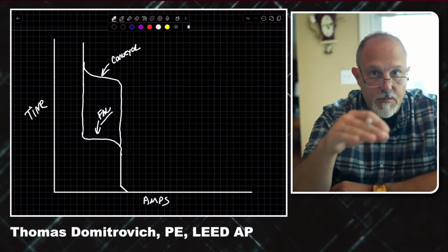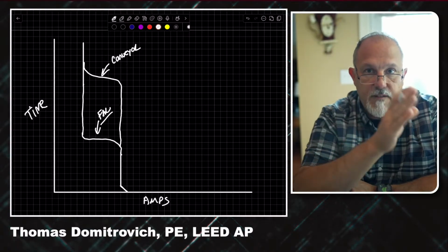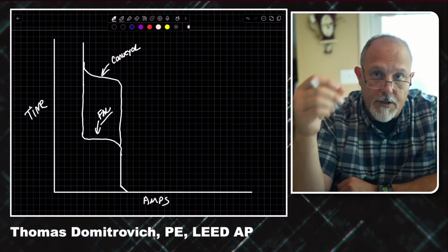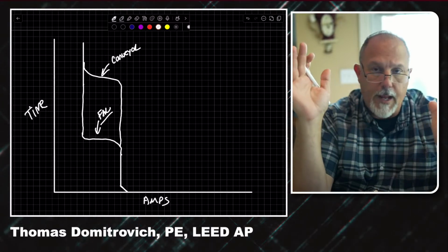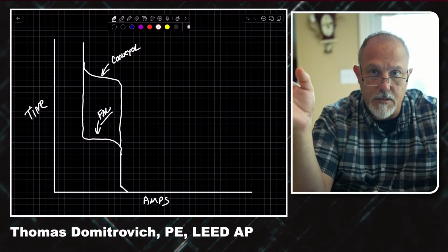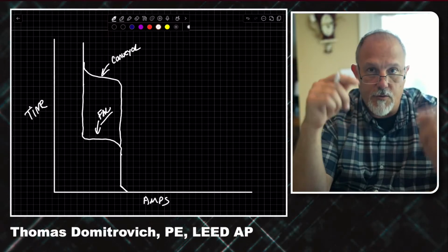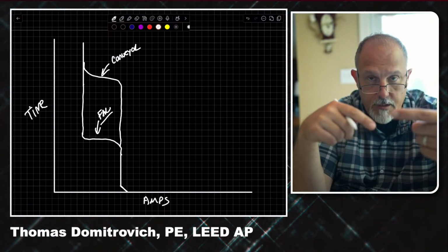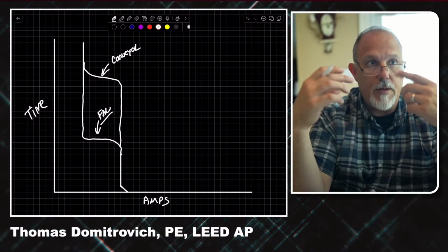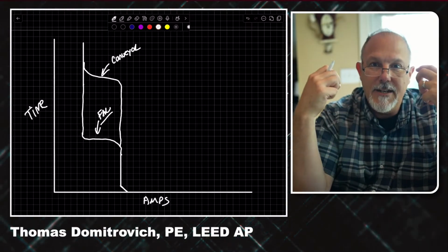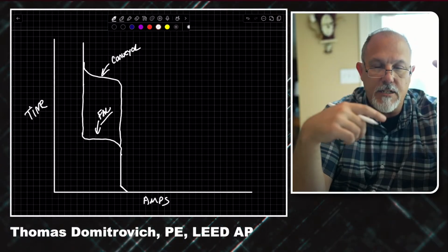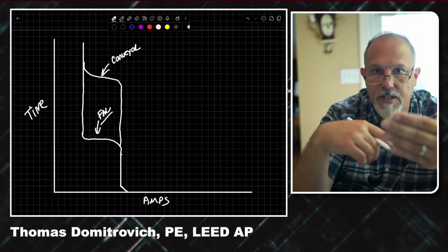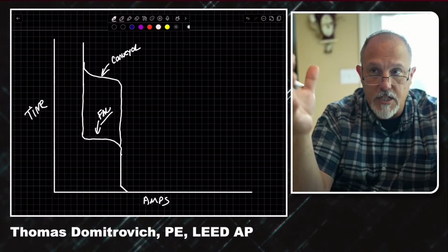And that transition point between locked rotor amps and full load amps on a fan, because there's very little resistance, can be very quick. You turn it on and it's at full load amps. And you're just doing the locked rotor amps to get that rotor turning and the fan turning. So it depends upon the weights of the blade. What is that fan? Is it just pushing air? The fan, is it trying to drive water? Is it like a pump? What's going on with the fan?